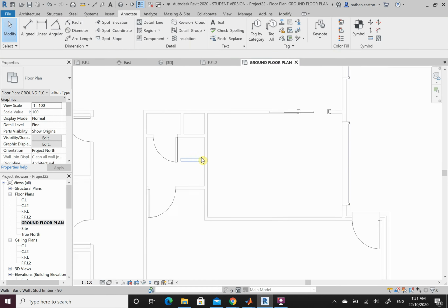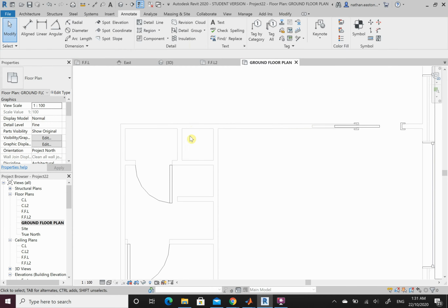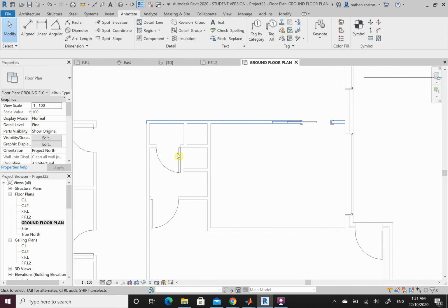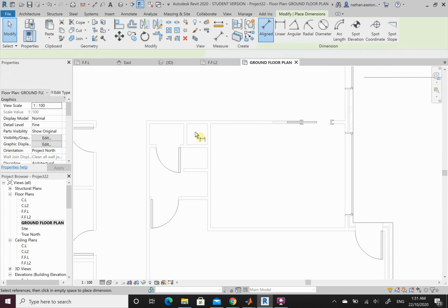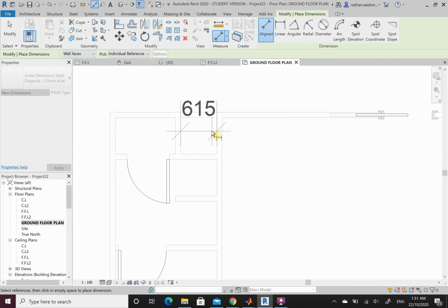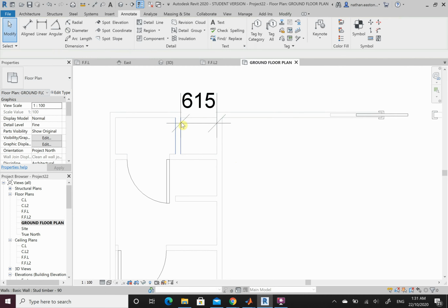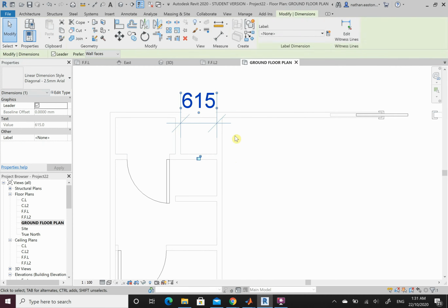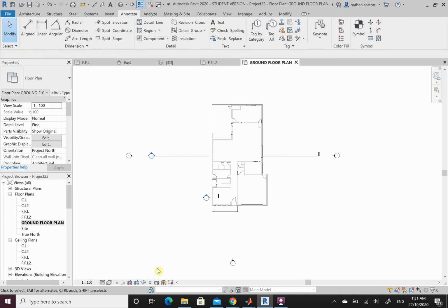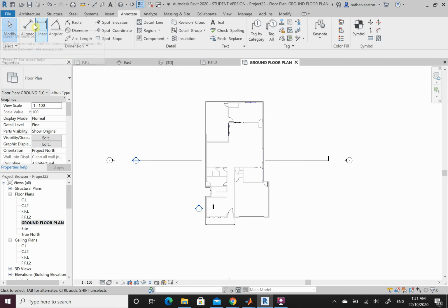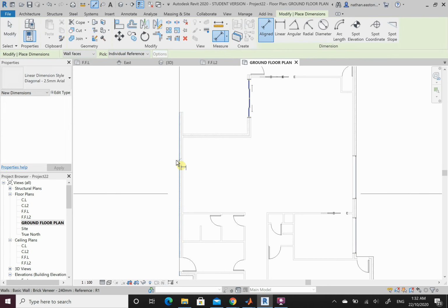The other thing is usually when we've got little areas like this, we might not annotate them on the outside. For our linens, we might actually leave minor text or very small text inside the floor plan. So we would reduce this to say 1 millimeter and hide it in here. So we'd go, width by height, and we'd hide them in there, just like you would have seen on the actual CAD floor plans that we've used. So you will need to go through and do your annotations in both directions for this house.